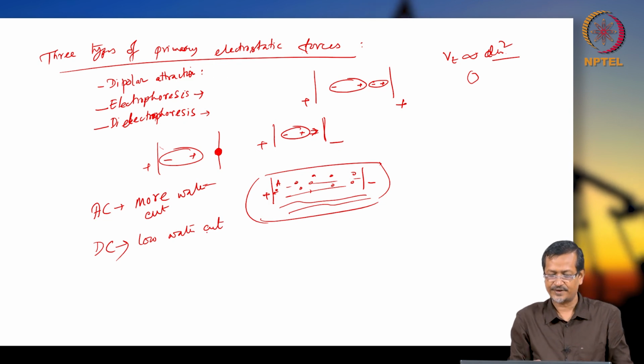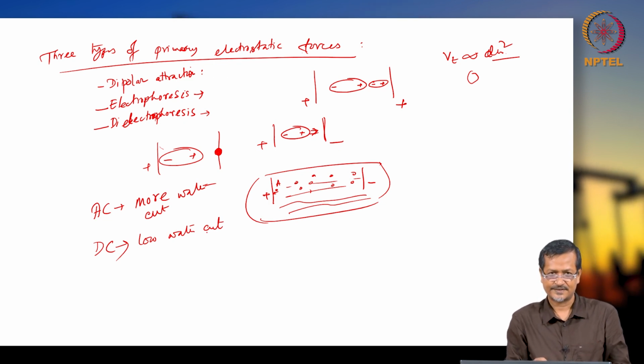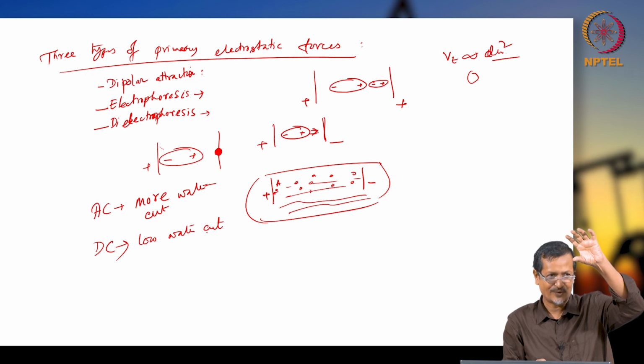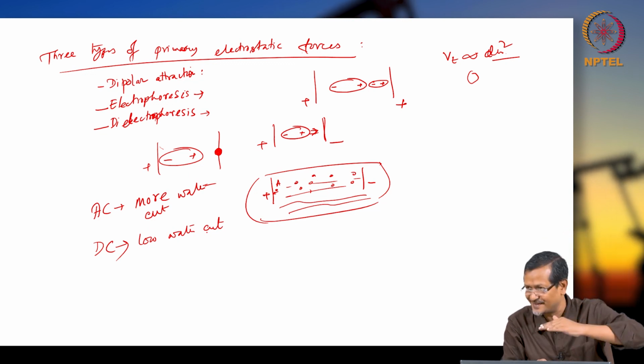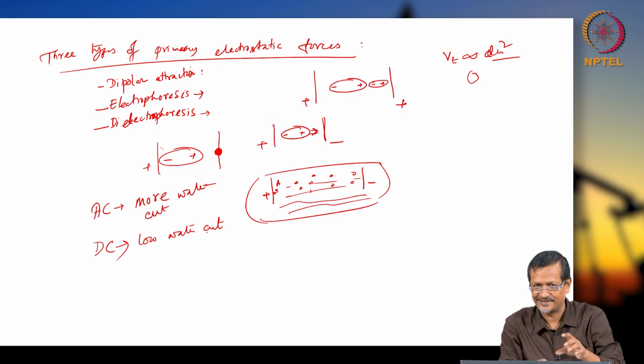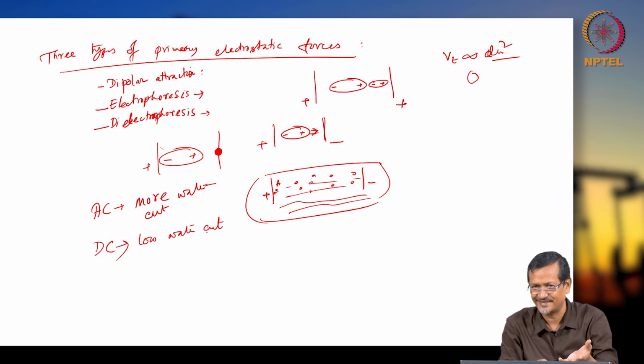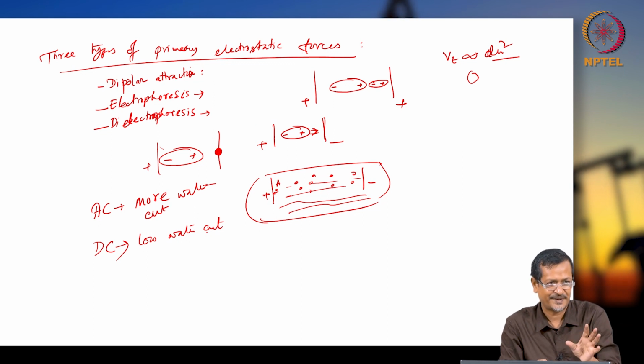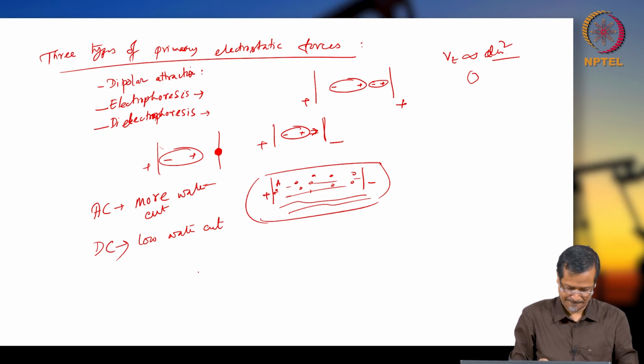So how do you create low water cut and high water cut? The separator's upper layer will have low water cut, a low amount of water, because water is getting settled. In the bottom part the water amount is higher, so you can create a higher water cut there. In that way you can separate. I have more information, I will explain.